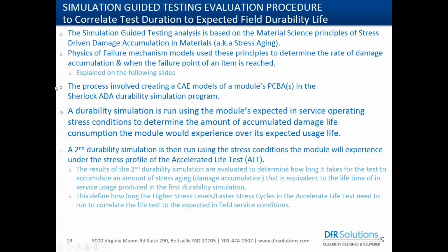The procedure involves creating, like I said, a CAD model of the module circuit board assembly and all of its components in the Sherlock durability simulation program. And we first run the simulation using the model's expected in-service field life operating conditions and stresses to determine the amount of accumulated damage, life consumption, the model will experience over its usage life.